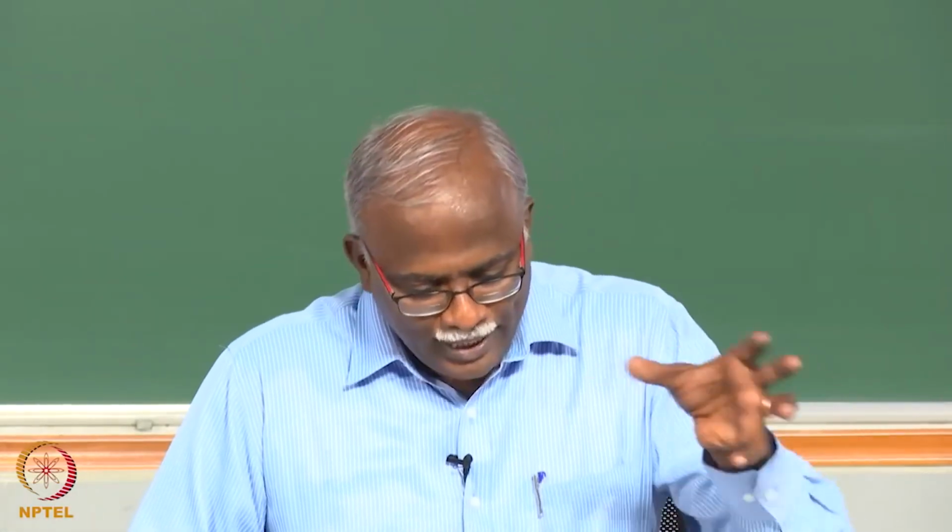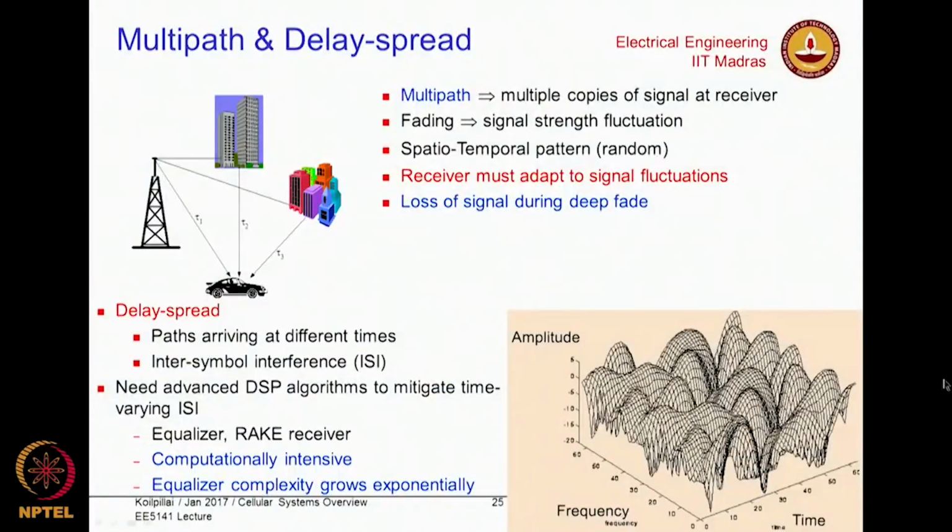So when you study these sorts of dense scattering environments, this is what we observe, that the signal is not always constant. At one point it is a signal with good amplitude. I move by lambda by 2, half a wavelength, and then all of a sudden the signal amplitude becomes very poor. Then again I move by lambda by 2 in any direction, and it becomes higher.